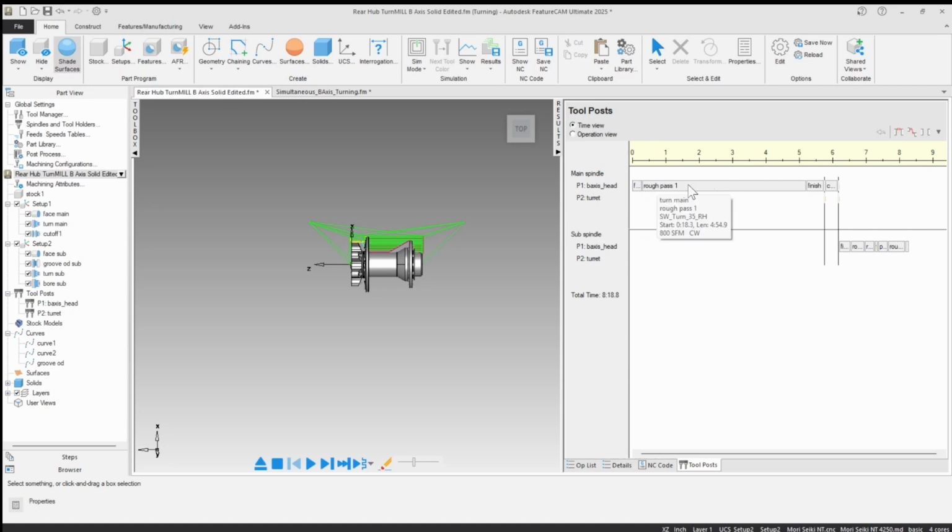And each of these has a little bar associated with it. And the longer the bar in this view, the longer that toolpath cycle is taking. So I can scroll my wheel on my mouse and zoom way in, and I can hover over the first operation. If you read the little pop-up there, it starts at 0, the beginning of the part basically, and runs for 18.3 seconds with those values. And then this one starts at 18.3 and runs for 4 minutes 54.9 seconds.